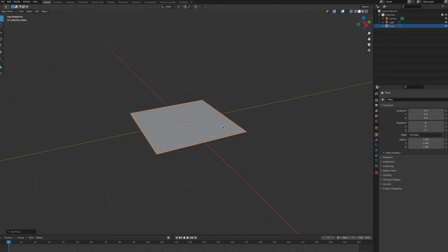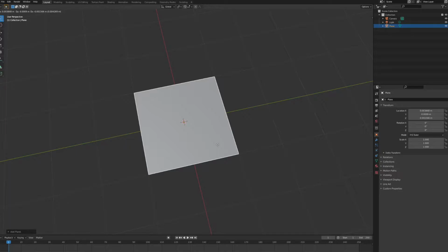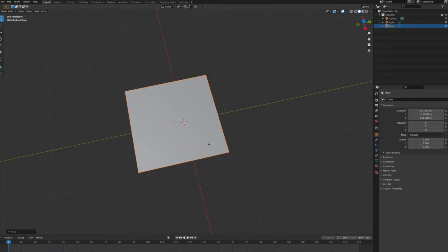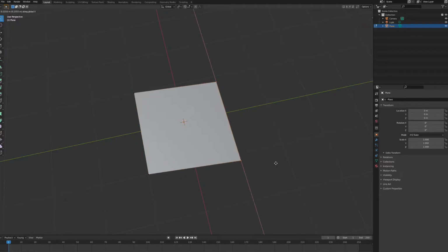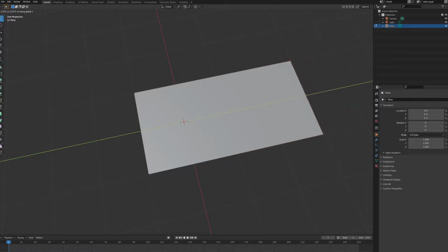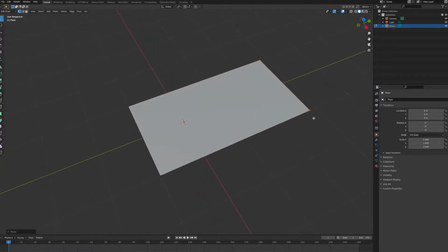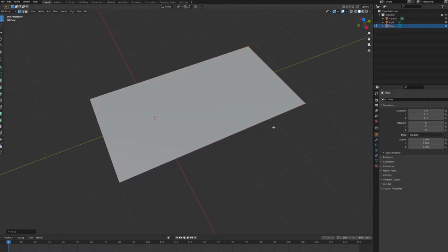With the plane highlighted, I can press Tab to edit the corner points of the plane. So I choose the 2 dots, and then I press G to move the shape, and then press Y to move the shape on the Y-axis only. This way I can drag the shape from a square into a rectangle.